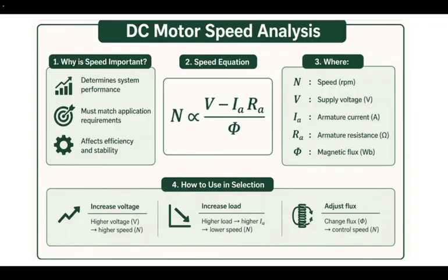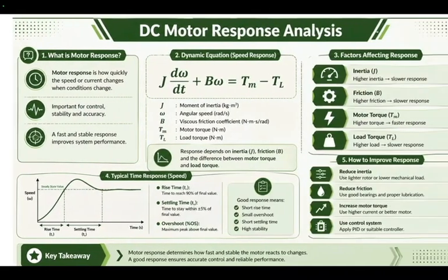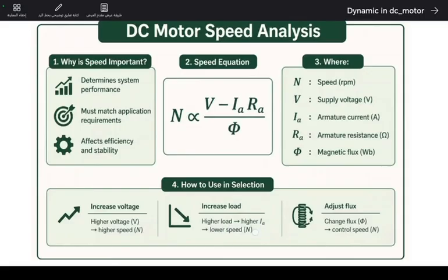Increase voltage, meaning higher voltage, higher speed. Increase load, higher load, lower speed, and higher IA. Adjust flux: change flux, control speed.